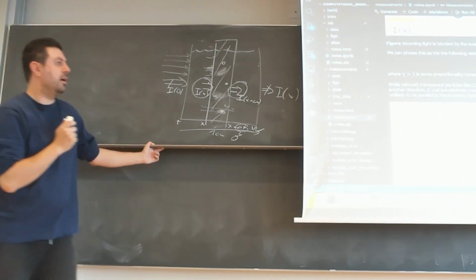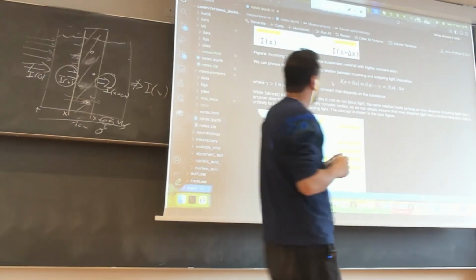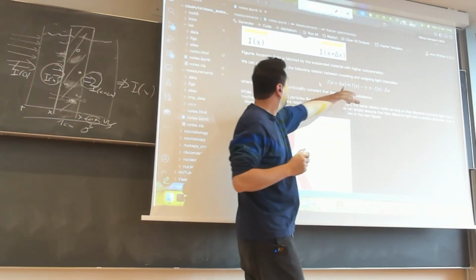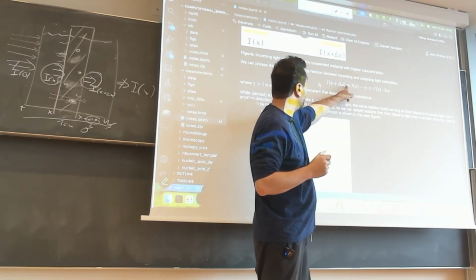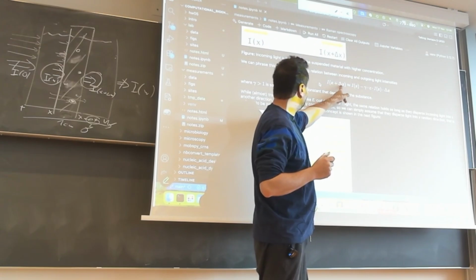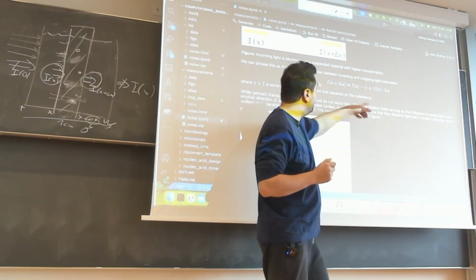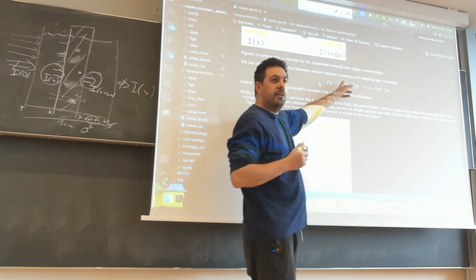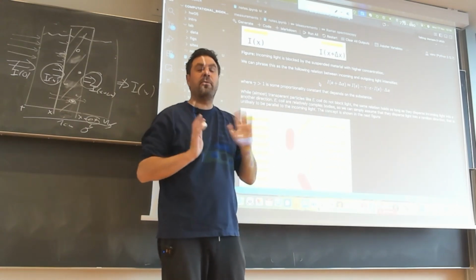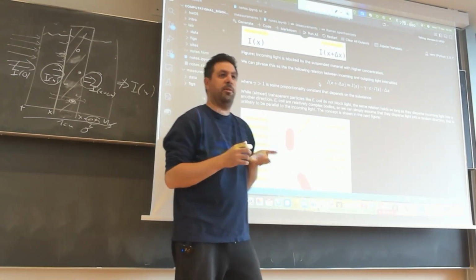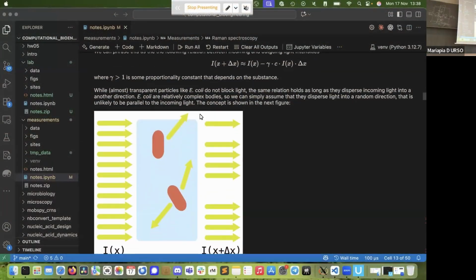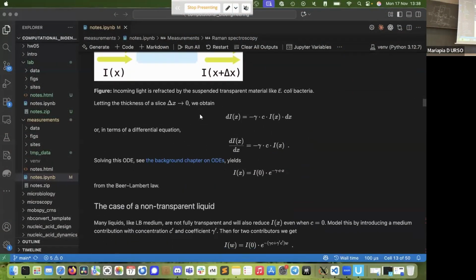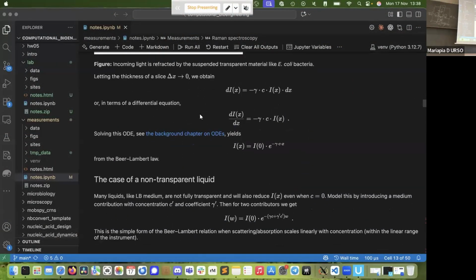And this is not too difficult because, I mean, you recognize, if you put this Ix to this side, you have I(x plus delta x) minus I(x), and then I divide by delta x. That's actually very nice, the differential operator of I with respect to x. So we were very lucky. And this is what is done here. You can look that up.